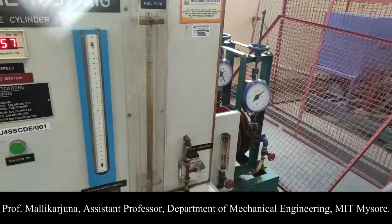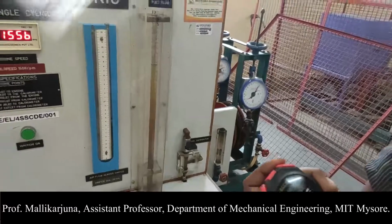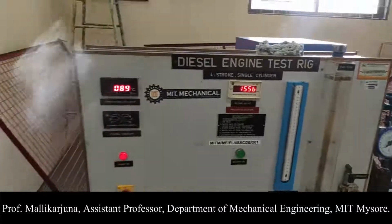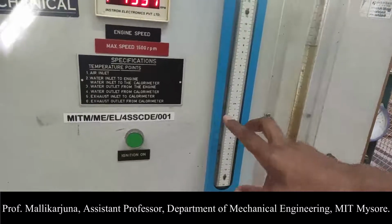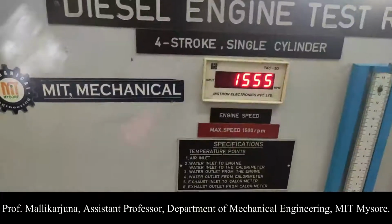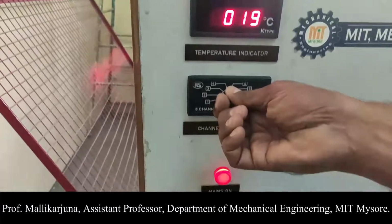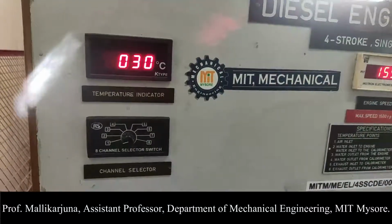Let us look at the time consumption for 5 cc consumption of fuel. This is the time consumed by the engine for the 5 cc consumption of fuel. Look at the mercury manometer limbs difference, which gives us the air pressure, and this is the speed with which the shaft is running. Again we need to note down the temperature differences: T5, T4, T3, T2 as well as T1. These are the 6 temperatures that we need to note down.